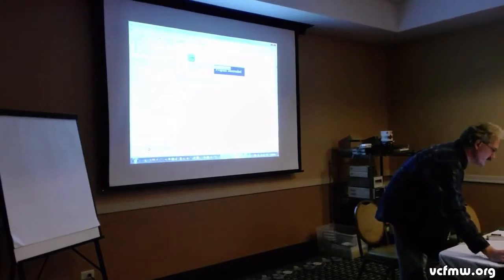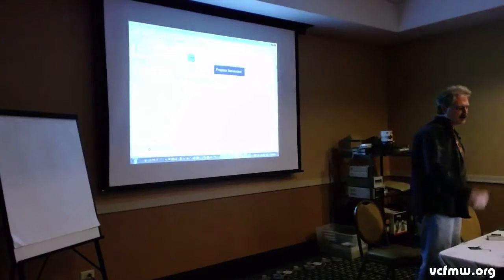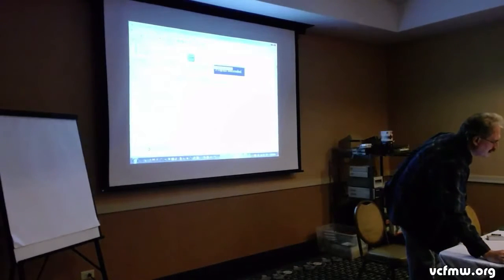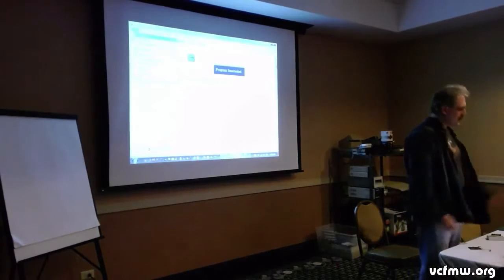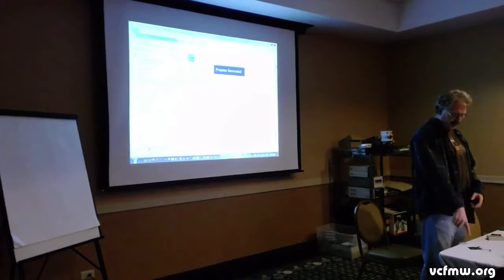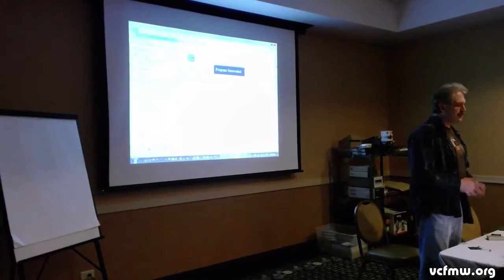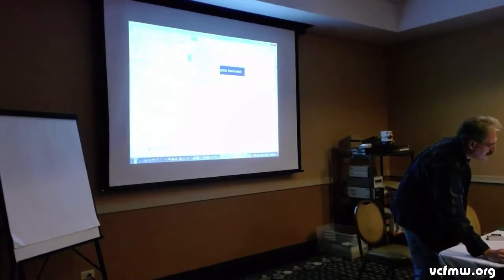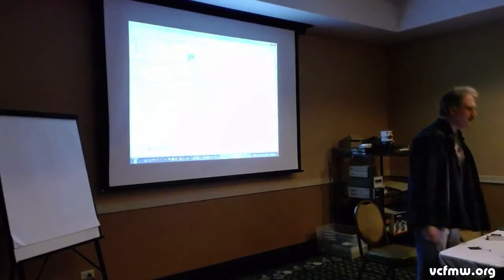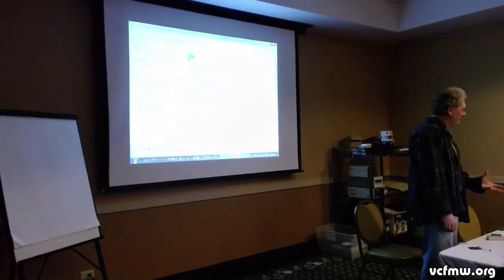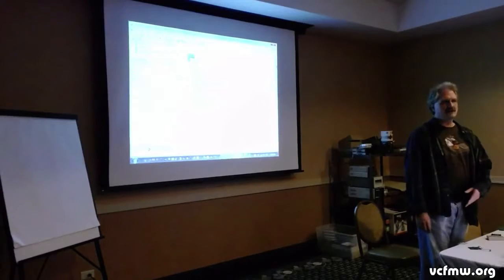I'm not going to do it. I can show you, if we go back to the main hall, I can show you this operate right here. But basically, you go over here and you can just open your project, and there's a part here that says wizard. There's a wizard that shows up. I think it's under file when I first bring this up. If you do the wizard, it'll find the cable. If you have it plugged into your little chip, it'll automatically find the chip, and it'll come up with the chip here being green, just like it is right now. And then you right click on it and you say program. And that dumps all the code right into the CPLD.